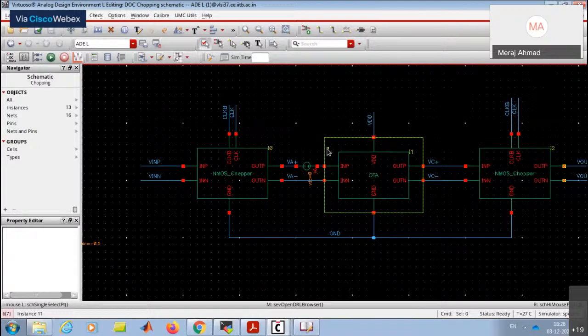There is a question about the open source LTspice tool. I'm not sure if PSS analysis is there. Only then can you simulate this type of thing in open source, because normal AC and noise analysis won't work with this type of circuit. Noise analysis is there, but not in so much detail.